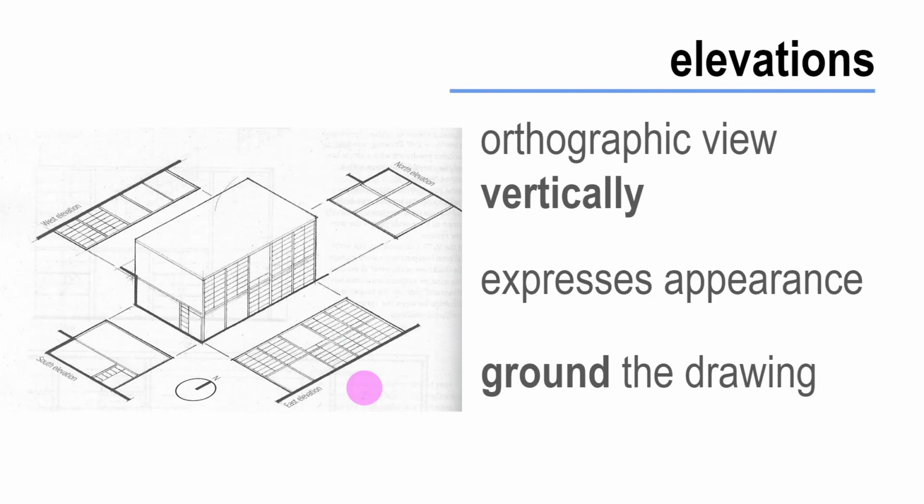And then elevation views translate best to those orthographic practices that I just showed and the orthographics that you are going to practice sketching out momentarily in class. So elevations are depictions of the outside of the building from the four principal views. We are typically going to define them as the north elevation, south, east, and west. You can have more than 4 elevations if you have a building that has a particular amount of sides and maybe it's a little bit more complicated, but often we just break it down into those 4 principal elevations.